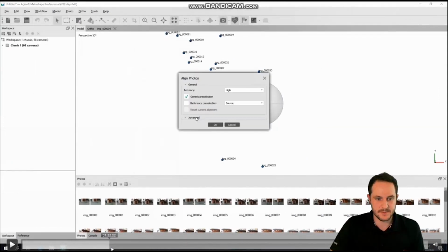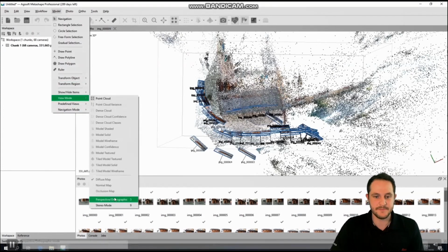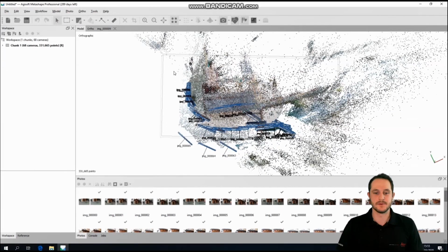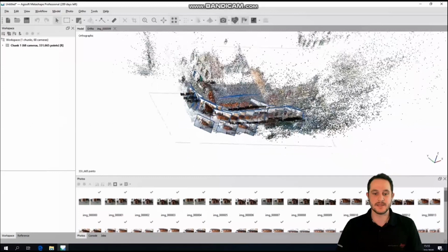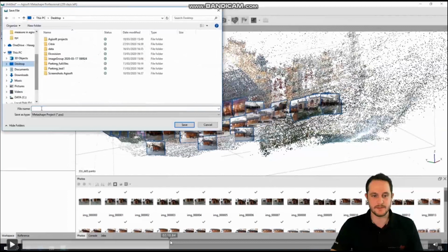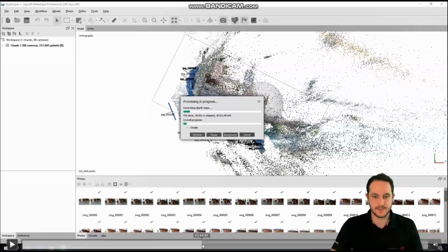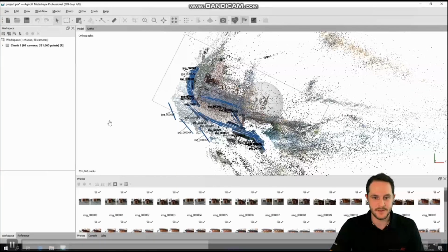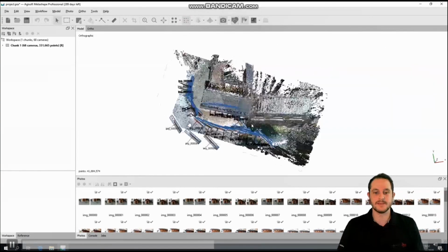And once this alignment is done, you have the photos aligned. And the next step, what you want to do is you want to create this dense point cloud. And this would be now the next step. So I'm just going to skip this model now. So there's a couple of steps you need to do in Agisoft to create this. But yeah, here's the process. And here is the result. So it will be now switched to Point Cloud, and now you can see the actual result.